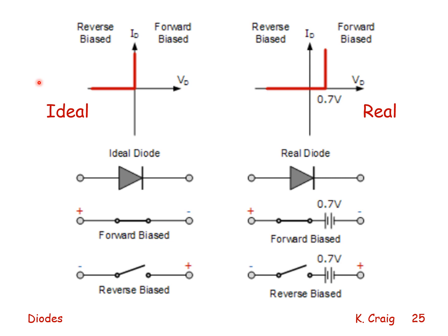Here we see two diagrams, one for an ideal diode, current versus voltage, and one for a real diode, current versus voltage. When an ideal diode is forward biased, it behaves like a short circuit. As soon as the voltage becomes positive, current flows. In the opposite direction, when it is reverse biased, no current flows. It behaves like an open circuit.